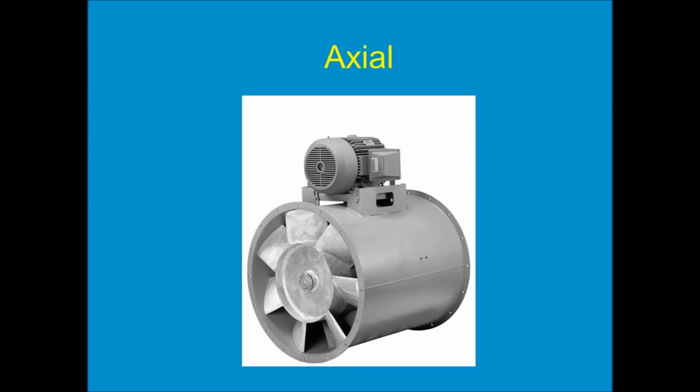So sometimes this type of fan is used in a medium pressure system. However, with an axial fan like this, the RPM required is very high, which means the noise is very high, and often the horsepower needed is higher than you would otherwise want to use.